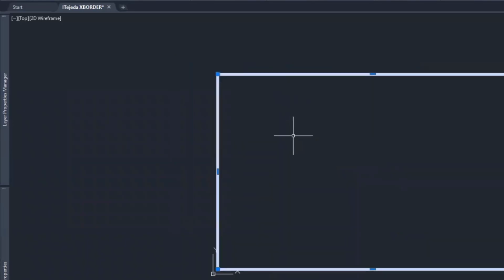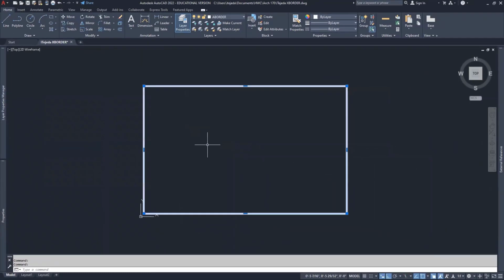You really won't know what this looks like until it prints. I always recommend that you do some test prints to make sure you have that thickness right, or you look at your architectural scale and take a look at a sheet of paper that is about the size of 11 by 17. Use the scale to check the thickness on the scale to see how thick of a line you'd like to make. I'm going to leave this entirely up to you.